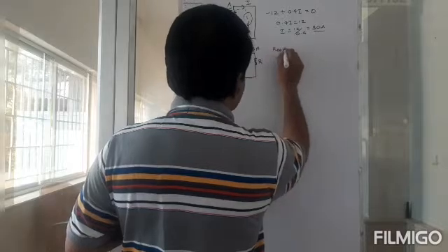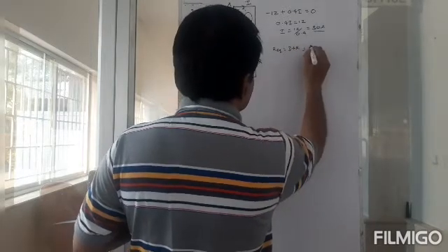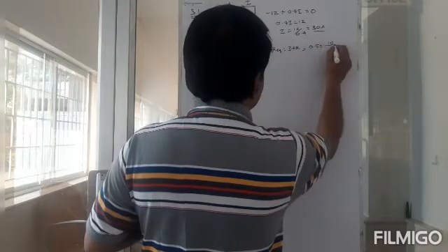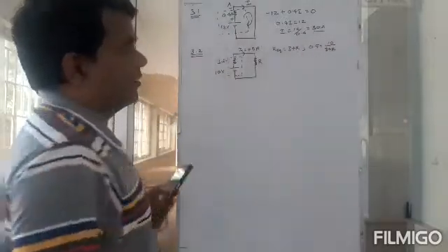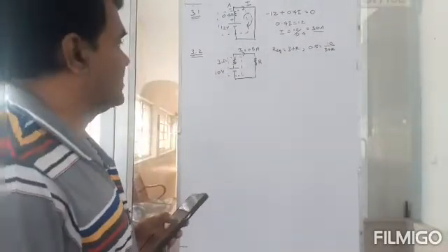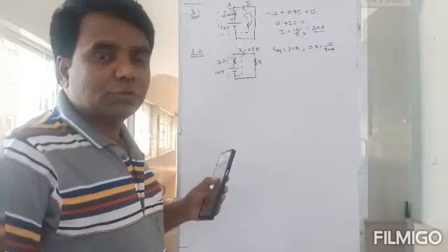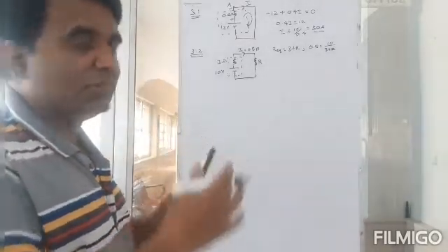Total resistance is equal to 3 plus R. Then the current is equal to 0.5, that is equal to 10 divided by 3 plus R. So using this equation you can find R. It's a very simple problem, but let me do it through the Kirchhoff's law method. Okay, so that gives you some practice, right?